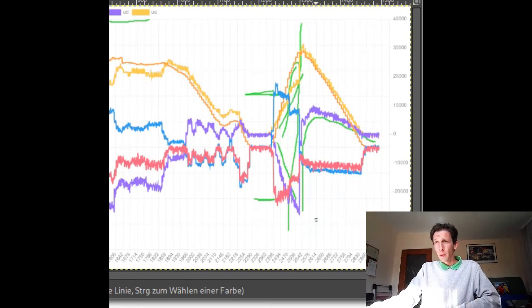But for this reason, your PI controllers need to be really, really dynamic to make this transition from negative to far into the positive really quickly. Because otherwise it will create current transients and they will usually trip one of the overcurrent mechanisms.